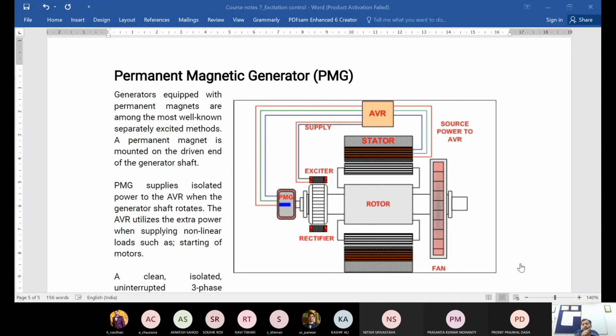If I plot the unmet reactive power demand on the x-axis and voltage on the y-axis, the voltage initially has a droop type characteristic, it keeps coming down, but then at some point it just collapses. So it's known as the nose curve: a gradual droop and then a sudden drop. That can occur if you are not supplying the reactive power demand adequately. It can lead to a voltage collapse and the entire collapse of the grid.